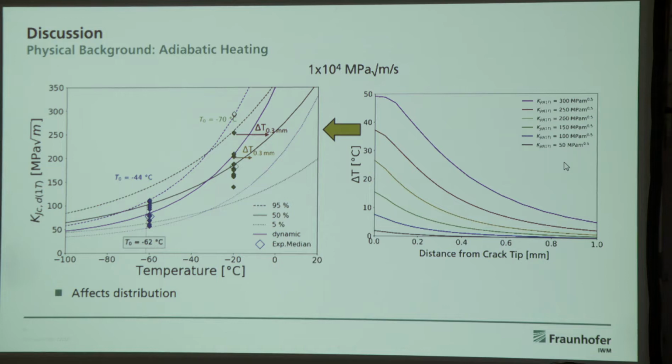So the question is, why is this happening? So again, I could talk about this in detail all day long, but basically it can be linked to two effects. One is very obvious, that is adiabatic heating, and the other one is not so obvious, that is local crack arrest.